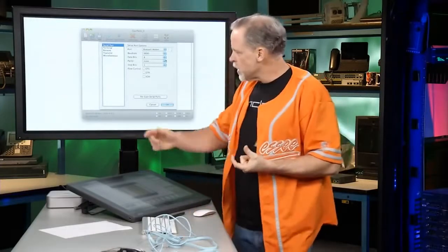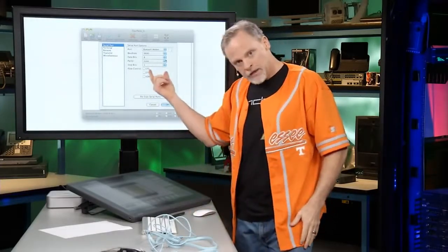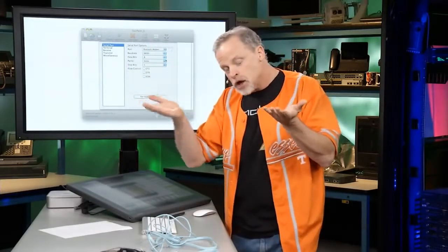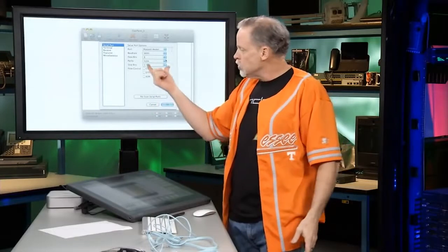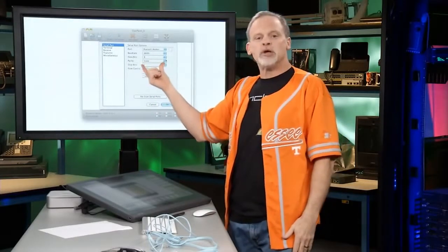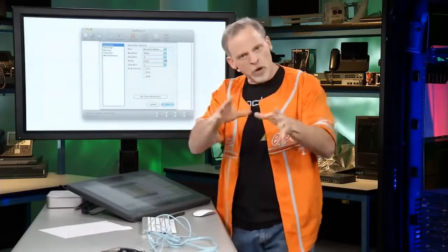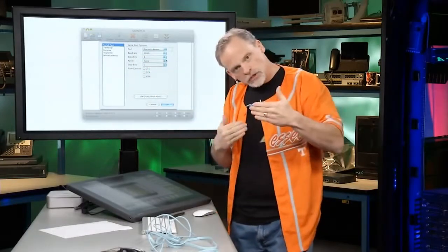And so to compensate for that drift, we'll say this is where this is going to stop. So while our speed is going to agree, we can have some variance in how that connects up, and we're always going to know when that frame ends because we'll see a stop bit. I expect a stop bit at 1, 1.5, or 2, and boom, that's where I know where these communications actually stop. It's pretty basic stuff, right?